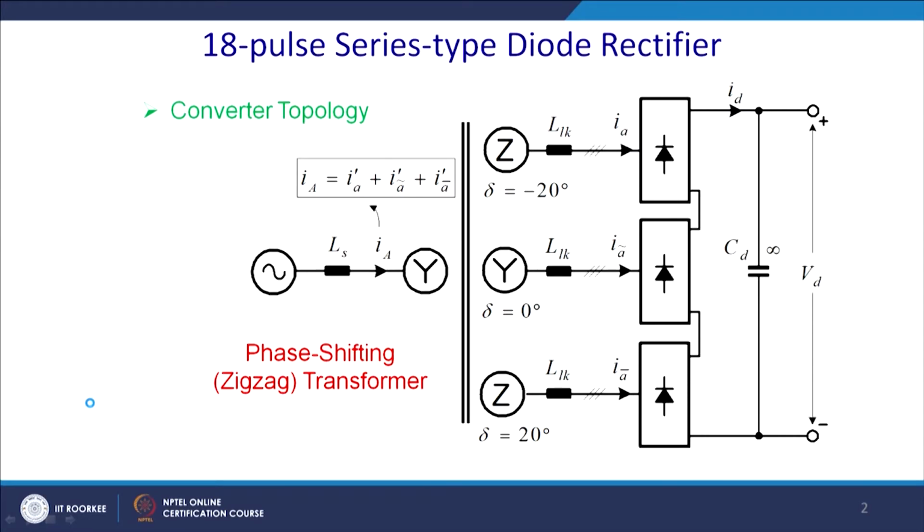Today we are going to discuss, in this second lecture on the multipulse converter, and thereafter we shall discuss the 3-phase PWM rectifier. So, first let us take up the multipulse converter. As we have seen in our previous class, a 12 pulse converter is quite easy: you require just one star and delta transformer, and this will be star and there will be